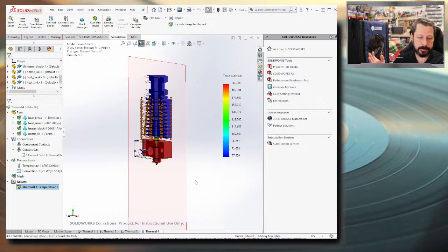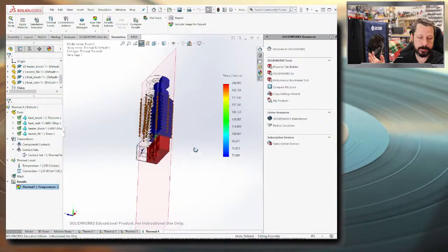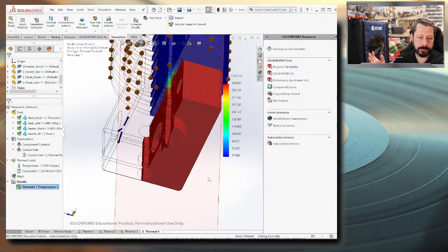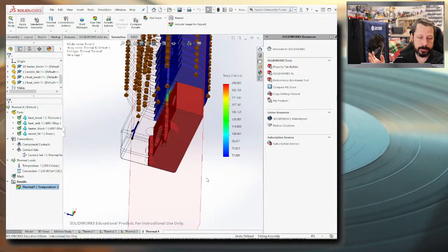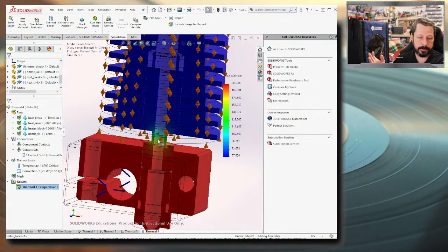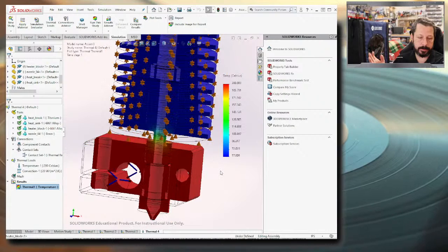So at some point you will need to replace the nozzle, and there's a risk there of at least two things happening. The first thing is you just go and unscrew the nozzle without heating it up, and the risk there is that it has seized in the aluminum block and you end up shearing the nozzle off, or you shear off this little neck right here on the heat break.